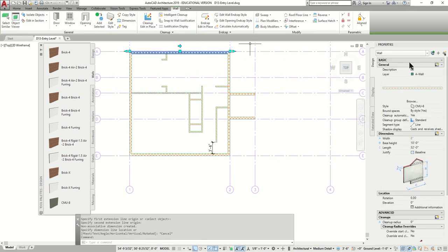So currently, if we look at the walls we chose for our exterior walls, they are 8-inch CMU thick walls, concrete walls. But if we want 3-inch thermal insulation and 4-inch thick bricks, we're going to need to change it for our exterior face. So we're going to need a 3-layered wall. So the next step is to change our exterior wall types we have around the house.